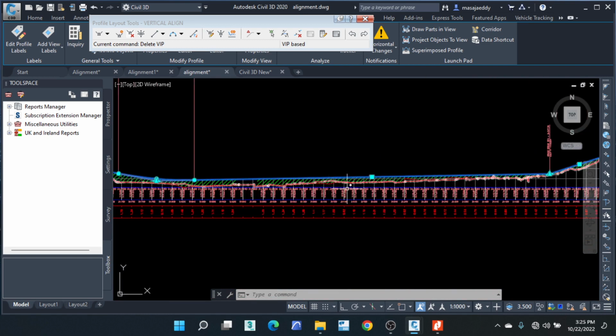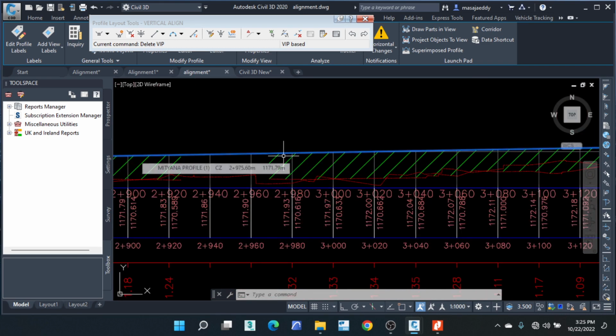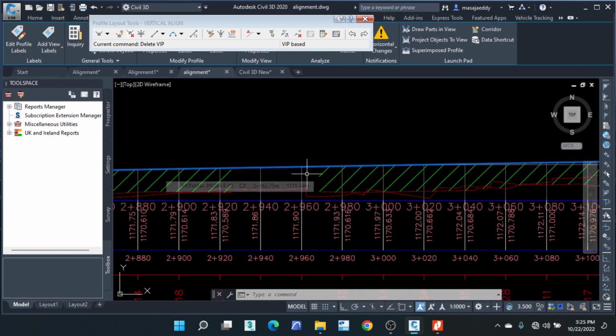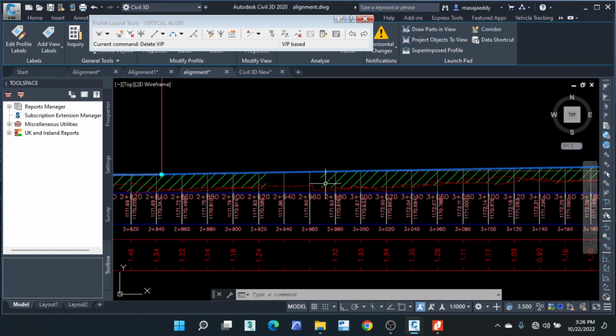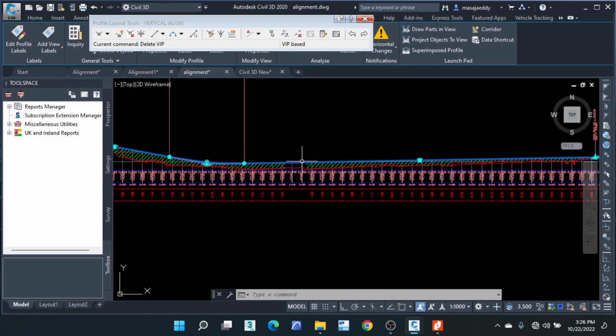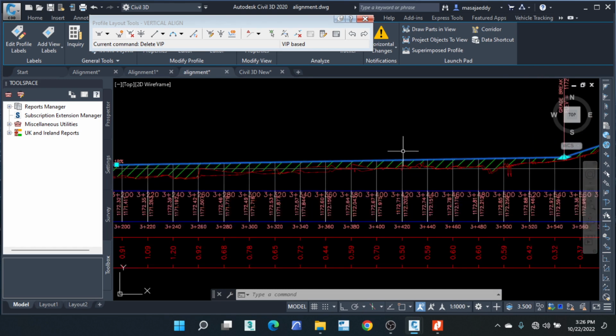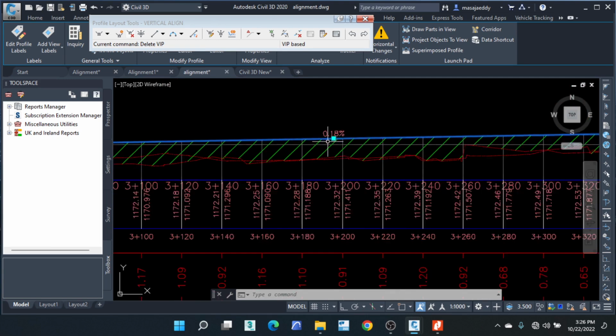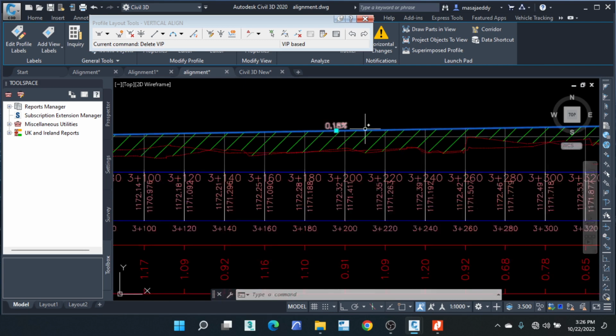So this area is a swamp, so you have to provide enough fill for the box culvert. Let's assume the level at the bottom of the crossing stream is half a meter from the existing ground as picked by the surveyors. So we add an extra 1 meter of fill on top of the culvert. Make sure as we pass through the swamp, we have at least a meter of fill. It's just an example. And also make sure the cross slope is at least 0.5 or above.